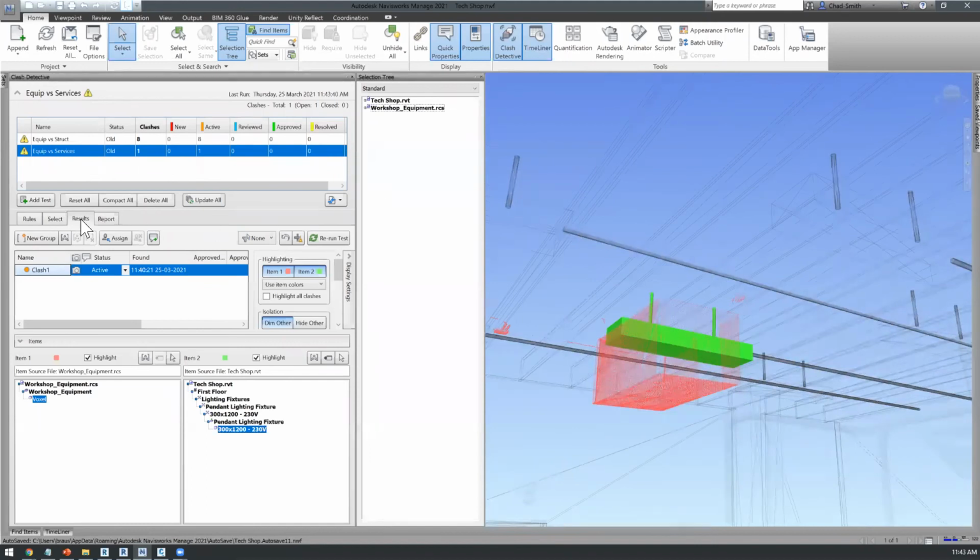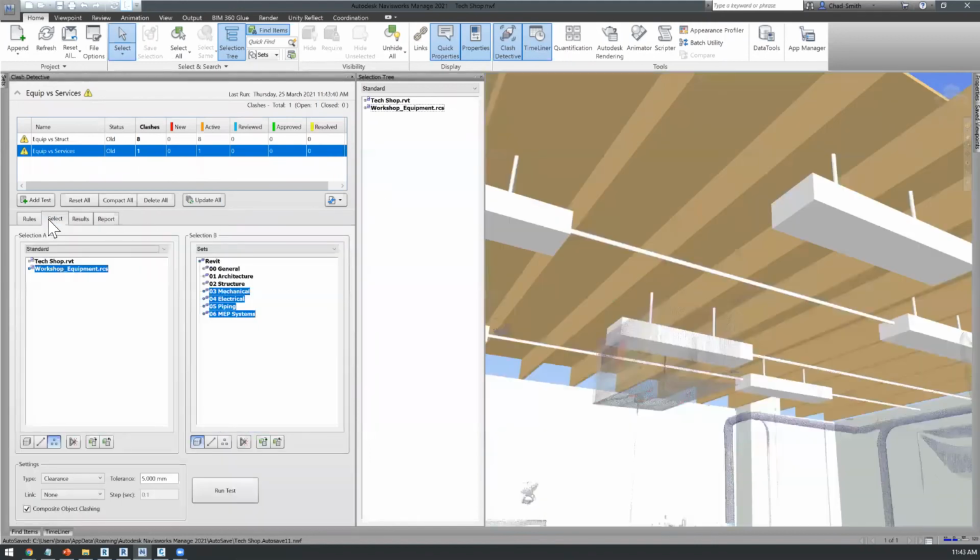Now, how we set this clash up is important. When I go back to the clash settings, looking at the RCS in particular, at the bottom of its settings, we're noting that we're checking against points rather than surfaces, which is the typical default option. This is important because we need to specify that this file has points, whereas the Revit file is clashing with surfaces.